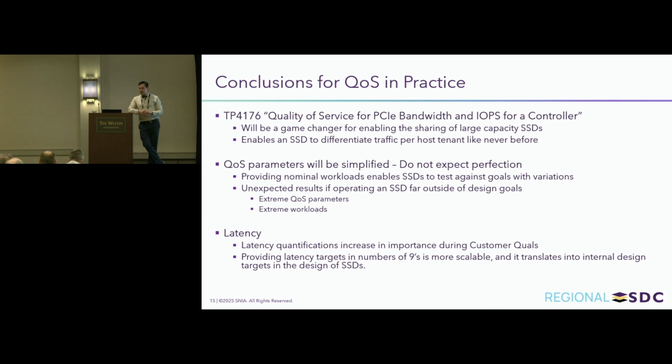In NVMe terminology, we've had things like migratable controllers and the migration management controller. There is something called a privileged controller, where there are privileged actions. The expectation is that in a typical SSD, a controller would get the privilege to set these parameters, and all the other controllers don't know that they're being set.